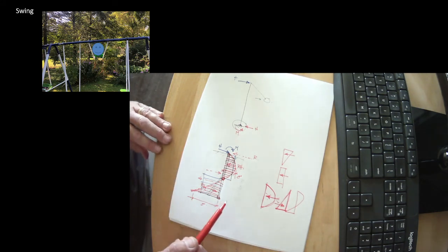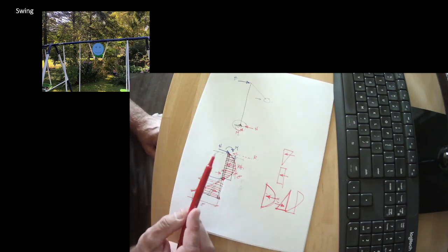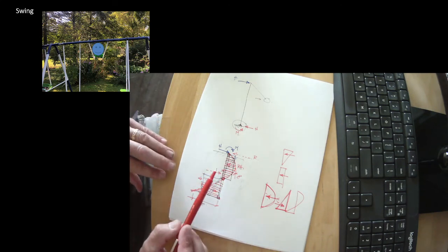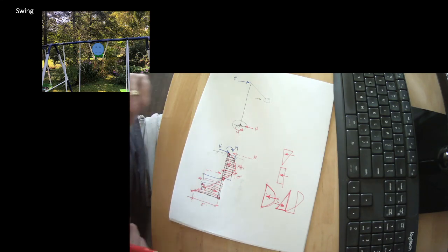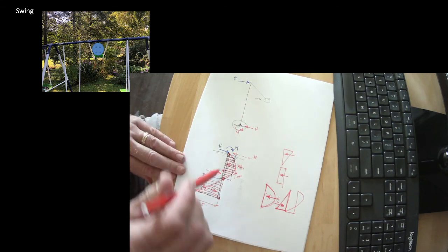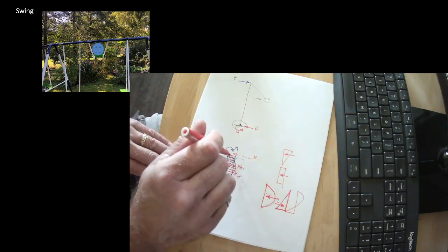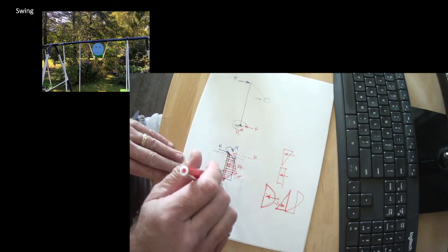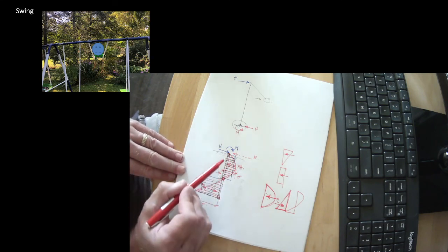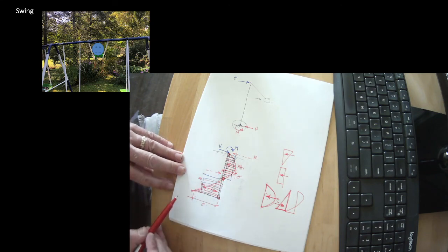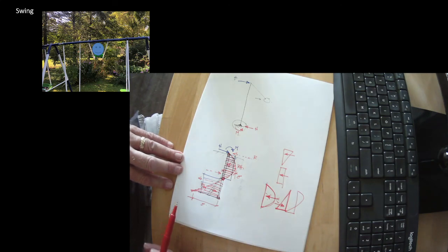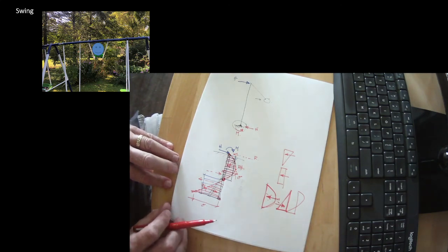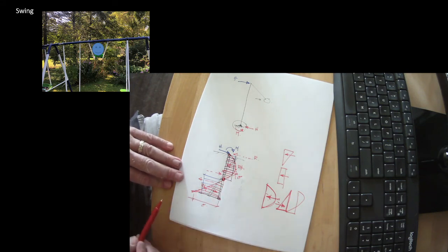So it appears to be, and it is, a very complicated problem. But as soon as we make a few very simple assumptions, the assumption being there is no force at the ground, there is no force at the point of rotation, we have a smooth transition between them, and whatever that curve is doesn't matter all that much. So we're going to use a parabola because it's easy to calculate. All of a sudden we have the ability to calculate our peak stresses on our lateral pile.